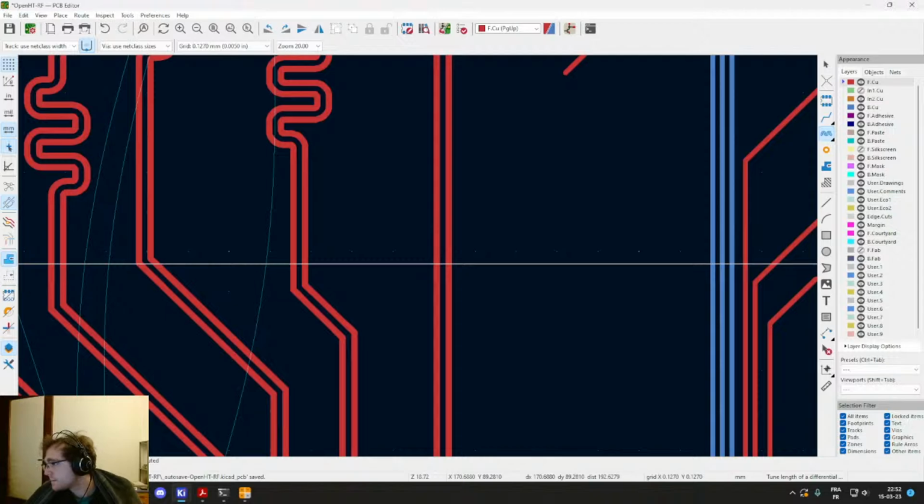ChatGPT says, okay, ChatGPT says a lot of things. Let's read that. So, ensure you are using KiCad version 5.1 or later, as earlier versions do not have built-in trace length tuning support. Yes, that might be true, but we are in KiCad 7 now, so it's good, which is quite new actually.